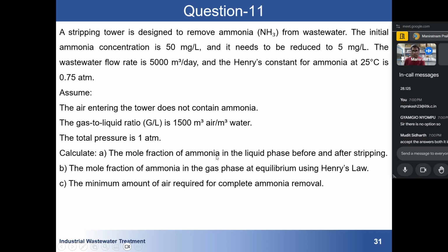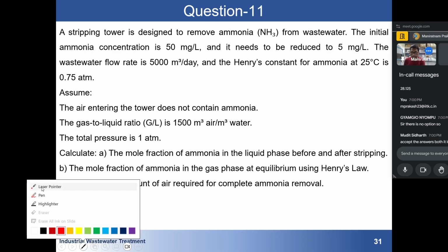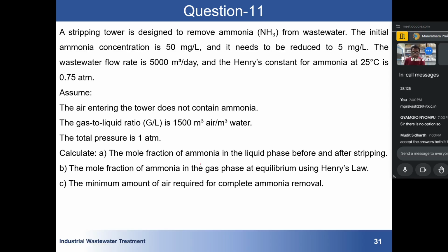Every data has been given to you. First you have to calculate the mole fraction of the ammonia in the gas phase at equilibrium using Henry's law, and the minimum amount of air required for complete ammonia removal.